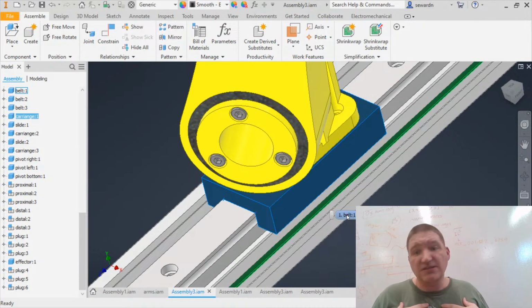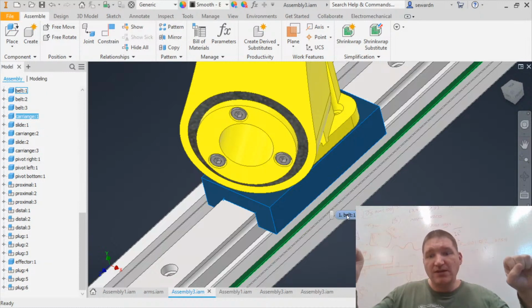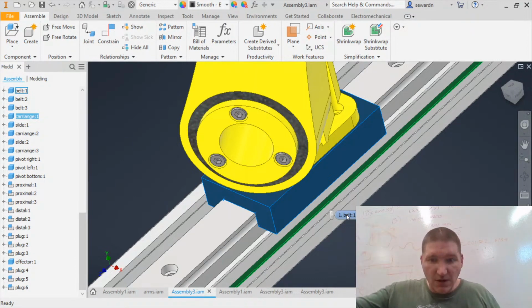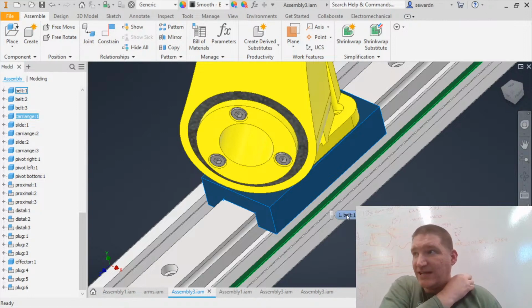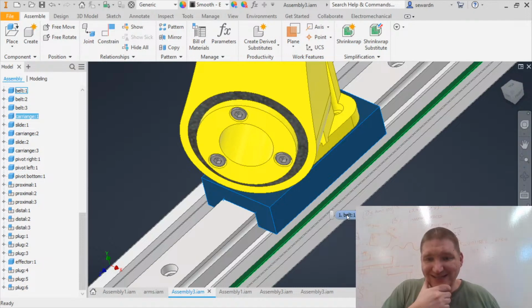I know there's a million different ways to drive this. Belts and stepper motors are very easy, cheap, fast, proven. So I'm cranking out a prototype, and I'm going to keep it all pretty basic. What are some other options, though? You can do a rack and pinion, of course. One of my favorite ones is you can have a static screw, and then you could have the stepper with the nut on the inside of the stepper, and it could turn and move along the static screw. That way you can actually have one screw and multiple steppers along that, so you can have a shared axis.